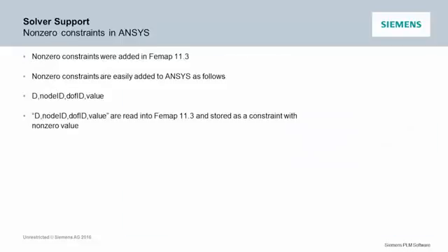Same thing that we did with the non-zero constraints in Nastran with the SPC, he did that also for ANSYS and Abaqus. So if those exist in your model, they'll get written out correctly so that they'll run the same in ANSYS or Abaqus. And he also did the CLS. I'd already told you the CLS and the CBUSH to ground. All those are taken care of.